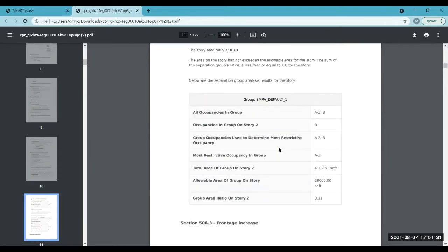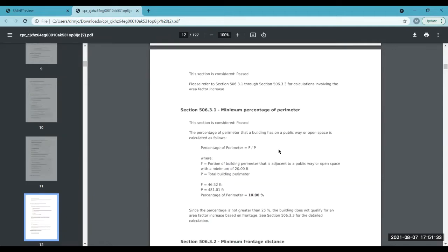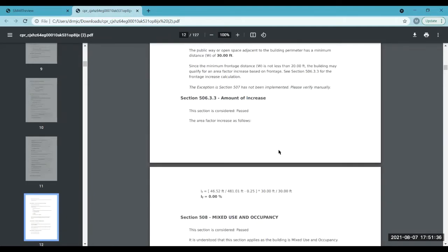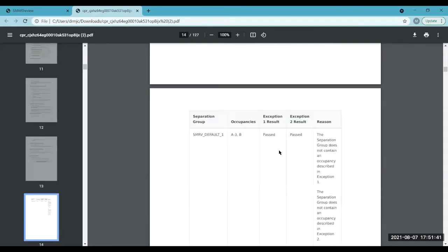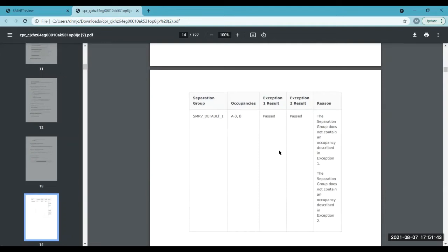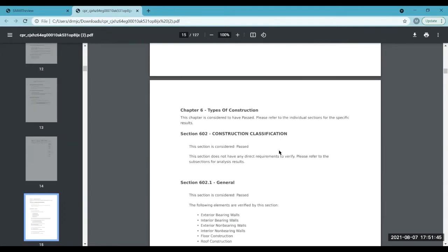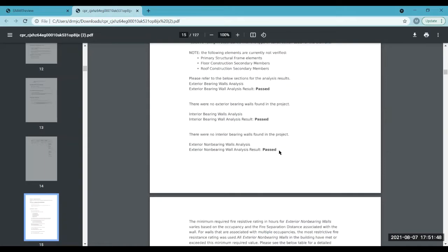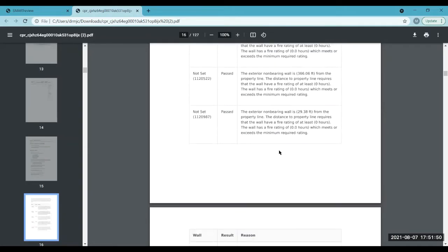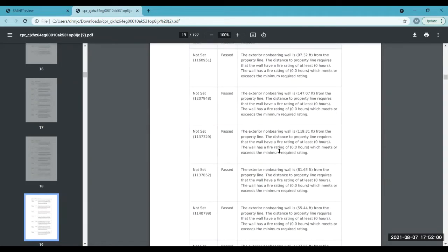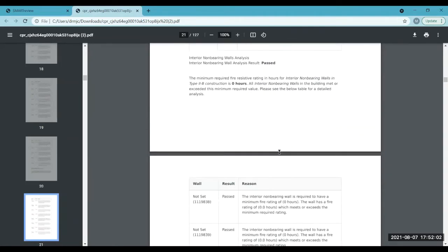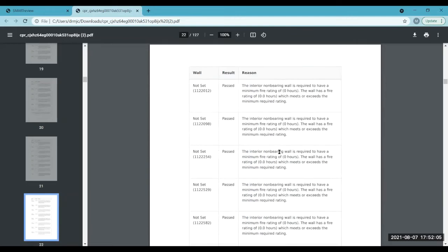For example, the height of the building is compared to the allowable height determined by occupancy code and construction type. The egress path lengths are compared to the allowed length, and the width of doors is compared to the required width determined by tributary occupant load that must pass through the door. The public official can compare measurements from the building plans to the calculations from the software to gain confidence in the results.